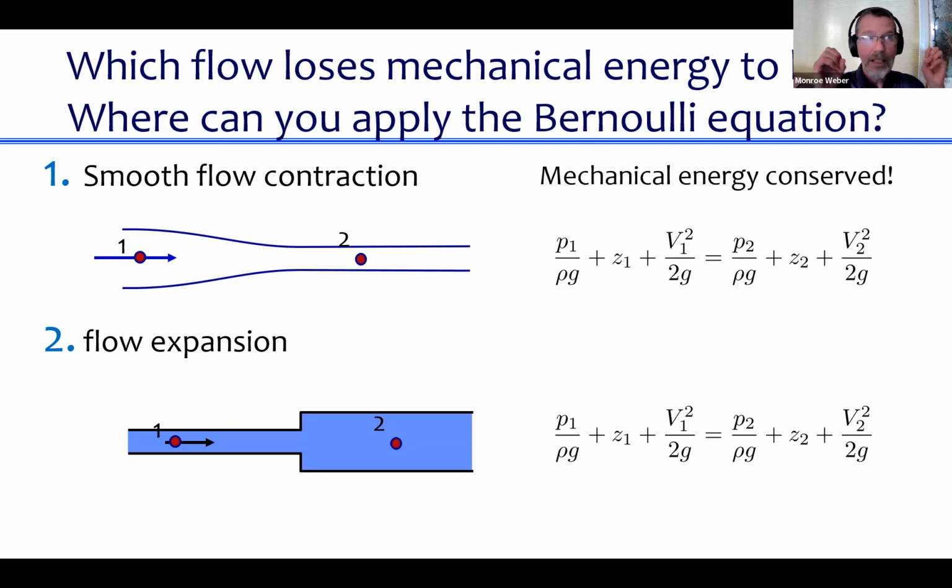And that high velocity means its flow has momentum, it's got inertia, and it doesn't know what to do with it. Okay, it's not actually a human thinking about this, but it's like, I need to slow down. What am I going to do with all this inertia? And it starts turning off to the side and creating eddies and spinning up and creating turbulence. And then that turbulence ends up dissipating a bunch of the energy.